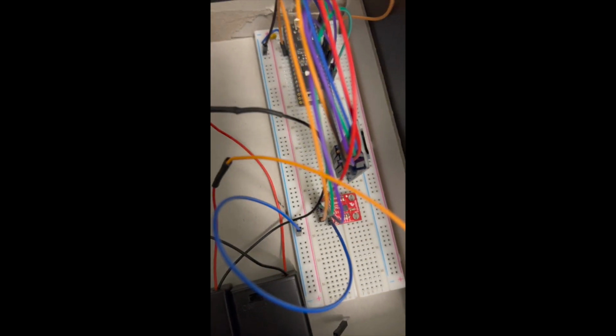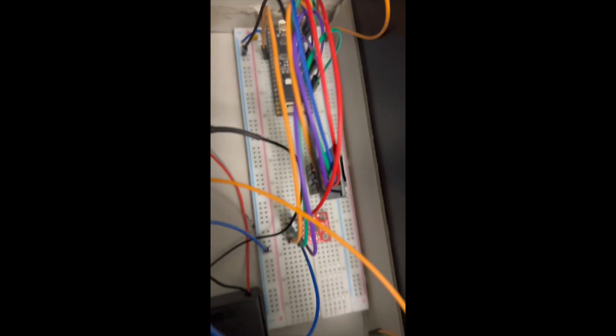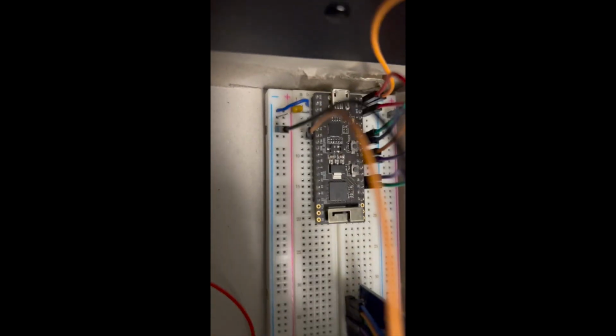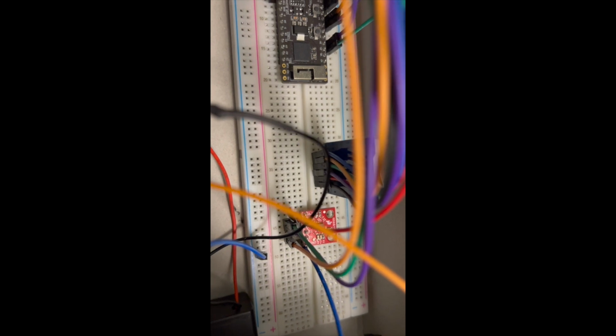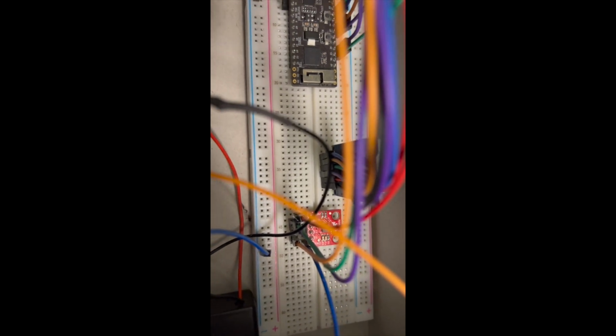All right, guys. The first step in explaining how this works is giving you guys a look at the actual wiring. So we can see inside of our beautiful Beats box here, we've got our ESP32, and we've basically got two things connected. The first is the SD card set up in a SPI configuration with those 4 communication wires there. The second is this little red chip, which is our accelerometer. You can see there we've got SDA, SCL, and the power and ground wires. So this is wired in a simple I2C configuration.